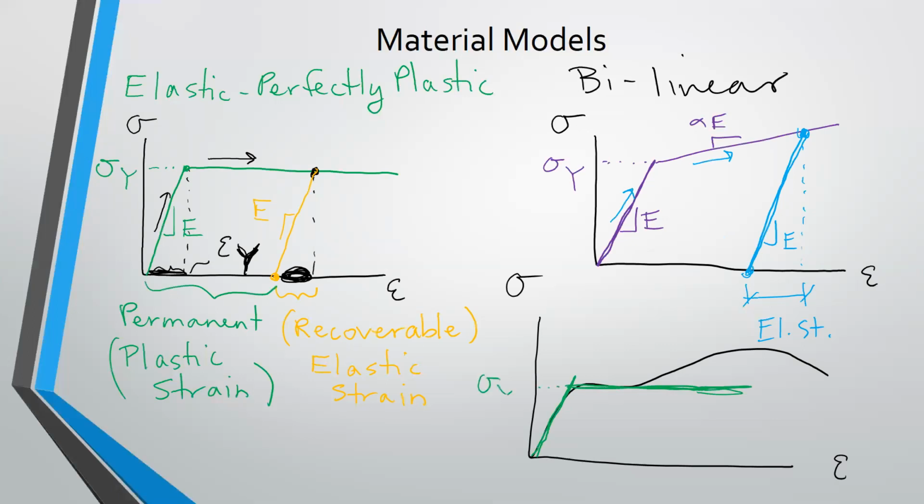And that point is your sigma y. And you'd call that your behavior. So as you can see, this type of model fitting might be good if you don't expect your material to go very far into the plastic behavior. It might approximate the beginning of that curve quite well. But if you're really wanting to put your material into that full strain hardening, then this may start to diverge too much from your actual behavior.